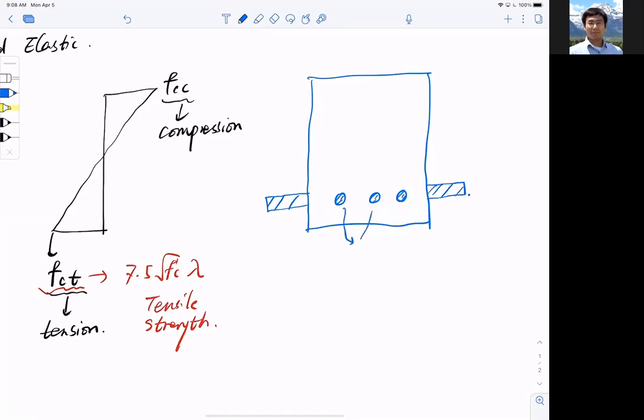So the area in the holes right here is As, that's the area of steel, basically. And outside here becomes (n minus 1) As, divided by 2, so this is (n minus 1) As divided by 2 on each side.